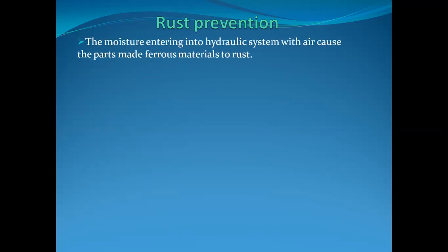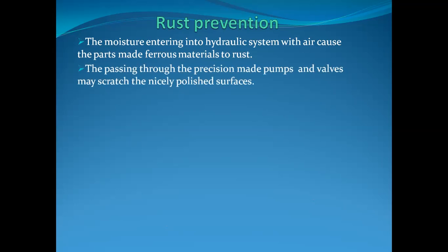The moisture entering the hydraulic system with air causes parts made of ferrous material to rust. If the rust forms, it passes through the precision-made pumps, that is, the minute parts of the pumps and valves. These are made very, very precisely. Therefore, if it passes through them, there is a possibility of scratches, and if this scratch produces rust, the scratch becomes rust.